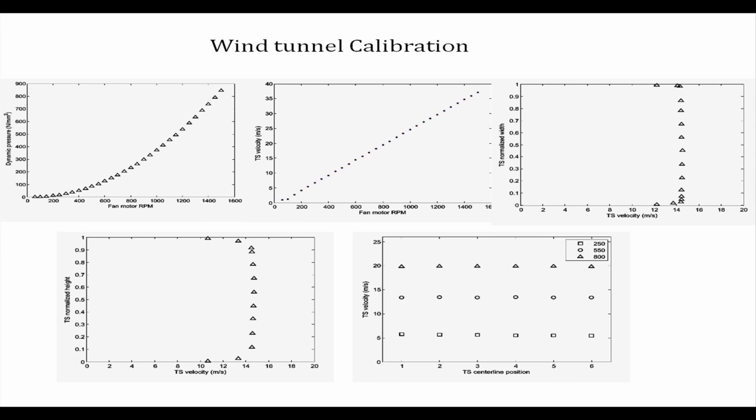If not 0, then very close to 0, because 0 will occur right at the wall, and you cannot have a probe sitting right at the wall, because the probe also has a hole and the hole has a thickness. And so, say the mid plane is still some distance away from the wall, that is one. Second point is that the moment you put a probe into the boundary layer so close to the wall, you will be further challenging it, because it is already out of steam there, and the moment you intrude there, it is going to stop anyway, because you are using an intrusive measurement method.